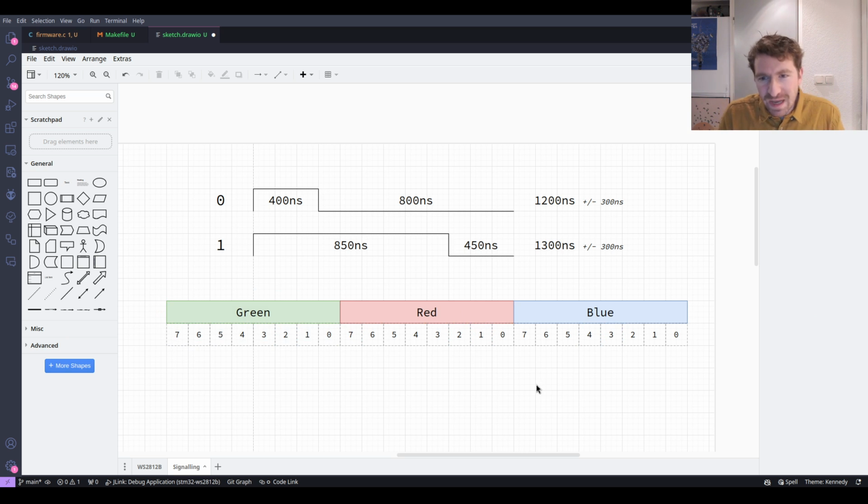So would you imagine that if you want to send bits for the green, you would just have a 0 volt, a kind of ground level voltage when you have a 0, and maybe a 5 volt or a 3.3 volt level when you have a 1. And you might imagine that's pretty common, but that's not the way it's done. In fact, this protocol uses a kind of non-return to 0 type encoding.